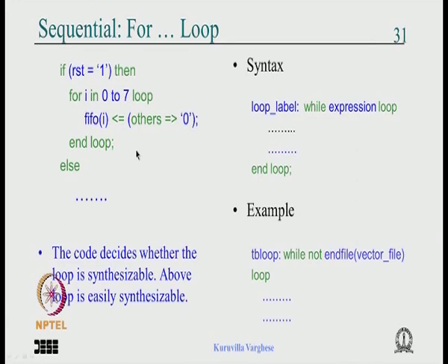And this is quite synthesizable. There is no issue, because, as I said, each FIFO location is initialized to 0, and this is an 8-bit location, and the FIFO has maybe so many entries, maybe 256 entries or 2K entries, it does not matter. It essentially means that for all the flip flops used in the FIFO, the reset is connected together, and when it is asserted it becomes 0.